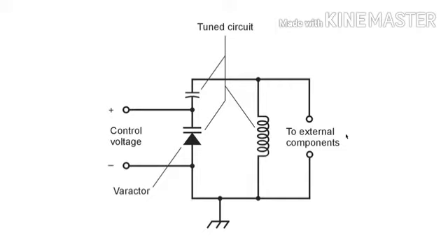It's easy enough to build a circuit like this yourself. You just need to use the formula for resonant frequency, remembering that the capacitor here, which keeps the coil from shorting out your control voltage, appears in series with this capacitor or varactor here, so you need to calculate the capacitance based on that series combination and then use the formula for parallel resonance.